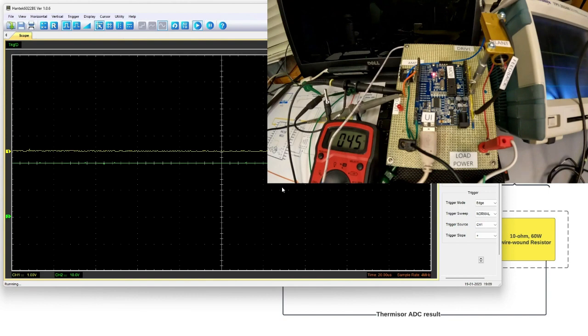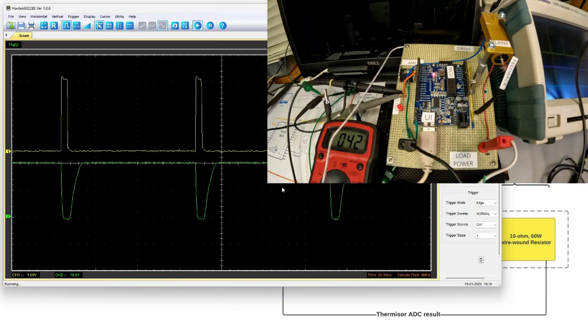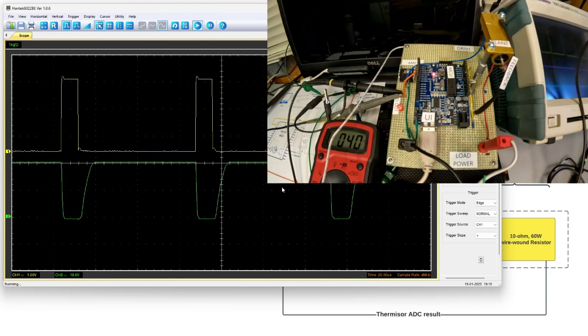And now we're reliant on the environment to draw it out of the aluminum block so that our thermistor temperature reduces back below our set point, and then our regulator will start to run again. Contrary to other systems, say like a DC motor where we can drive the voltage positive or negative, we can drive both ways, but here we can only put heat in. If we had a piezoelectric cooler or some other mechanism to cool that block, we could do that. But you can see that by natural convection, that temperature is coming down again, 43 degrees C, 44. If I turn my fan on, it'll bring it down more quickly, and we will start, as you can see, to actively regulate again. So now we're needing to pump energy into that resistor to counteract the convection loss.